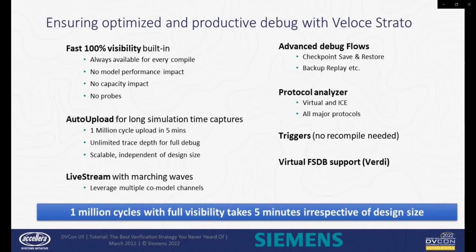You will be able to upload for long simulation. For instance, 1 million cycle upload in 5 minutes, and this is irrelevant of the design size. The whole architecture allows you, for a small or big design, to get the same number. In addition to that, you have live stream capability, which allows you to send the information for your key elements outside the emulator without getting any degradation on the performance for the entire running of your test.